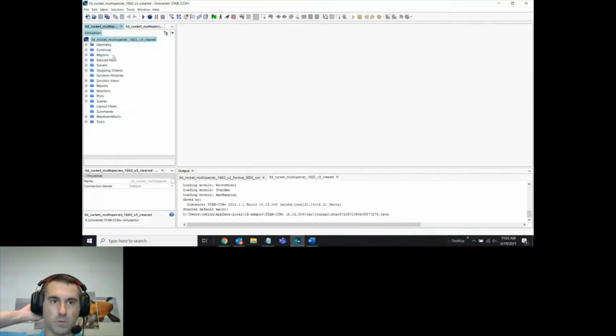Okay, so if you go into our community site, there's actually a link to the simulation that I'm showing you here. What you can do is import your geometry into this and start working off of it. There is some pre-built geometry in this, and that is fed into the simulation process so that if you're making changes in the future, if you want to change the size of your fins, or if you simply want to make different boundary condition changes like atmospheric changes or pressure changes to your chamber, it's very easy to iterate on that. But either way, I'll go ahead and start.